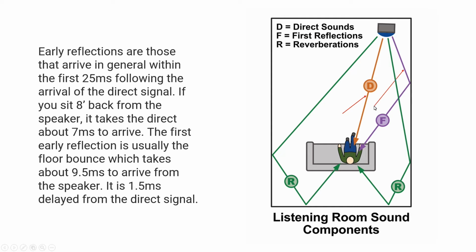And then we have so-called first reflection sound. The first reflection sound reflects from the nearest walls, and it will come within 25 milliseconds. When they come within 25 milliseconds, they are considered as one signal. As direct and reflected, we hear it as one single signal. And then you have so-called reverberation. When your signal path is longer than 25 milliseconds, you are hearing it as echo.